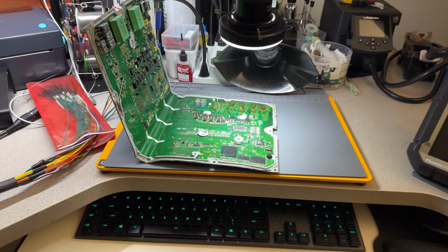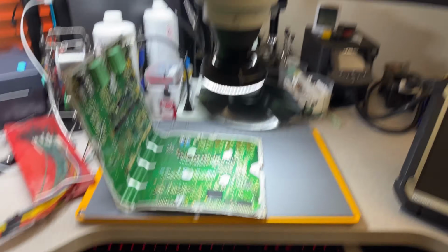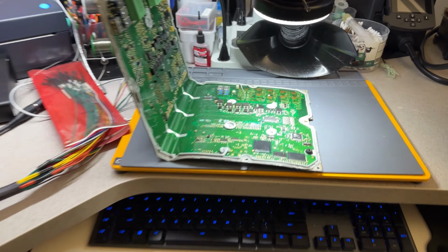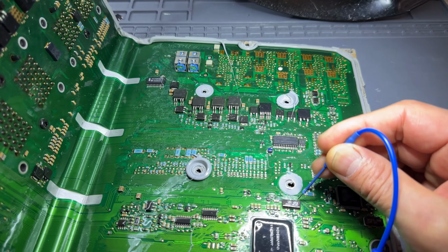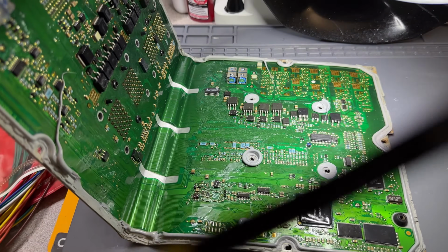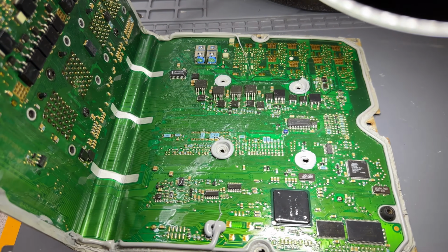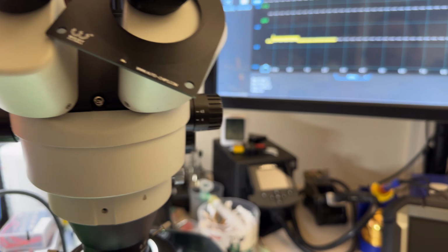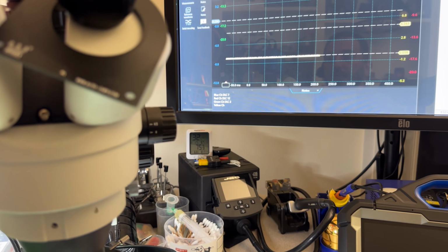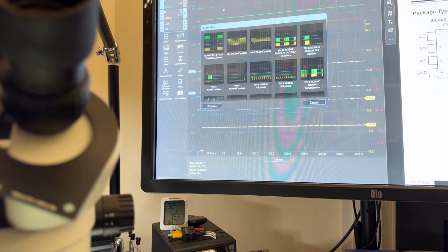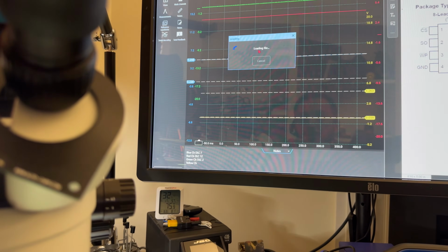So I want to transfer these to a known good computer. Again, power on, we saw the voltage rails, nothing. And another thing I wanted to show you is the clock. We've got an oscillator here. Let me move my microscope so I can see. I'm going to have to change the speed because I'm at 1 second per division. This might be a lot faster than that. Actually, let me open the folder.